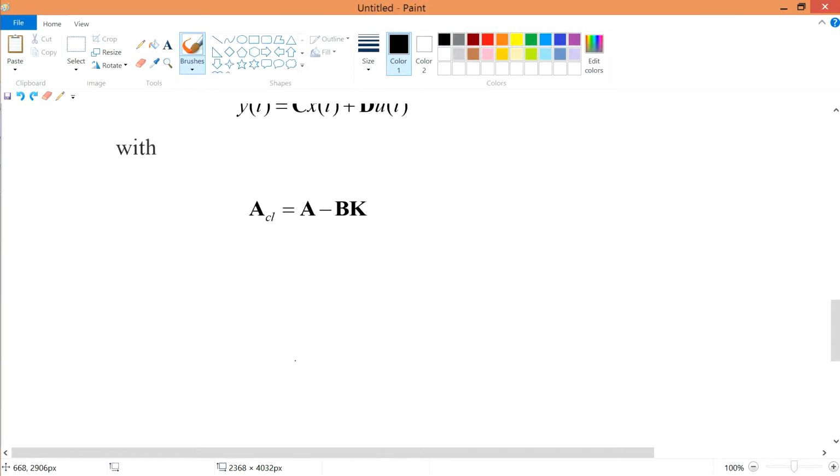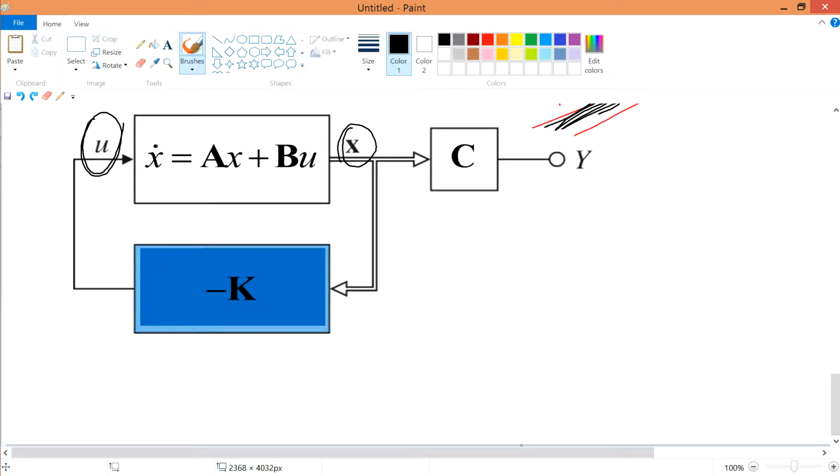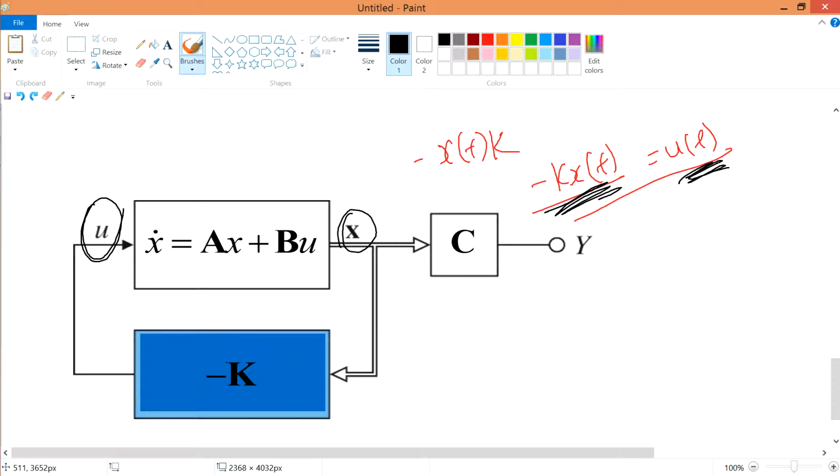Just now, what we drew is a closed loop coming back to u. This may not come naturally, but it is in fact a feedback system. If you talk about a certain transfer function, say G(s) equals Y(s) over U(s), then the denominator is called the characteristic equation.